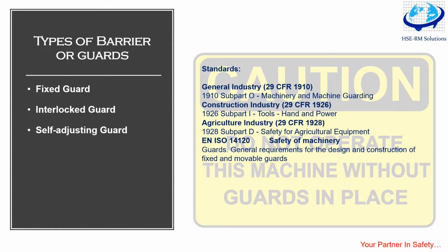The guard may consist of a safety fence, barrier, cover, or similar. It may be welded, glued, or attached with fixing systems like bolts and rivets. Fixed guards make it more difficult to access the machine physically. Fixed barrier guards must be secured with at least one fastener requiring a tool for removal.